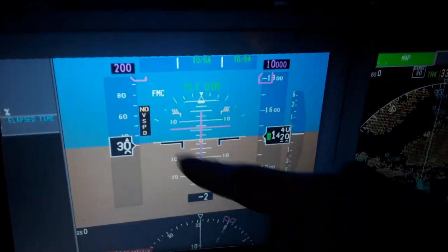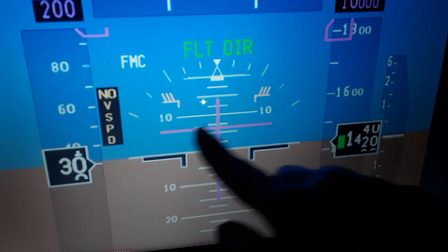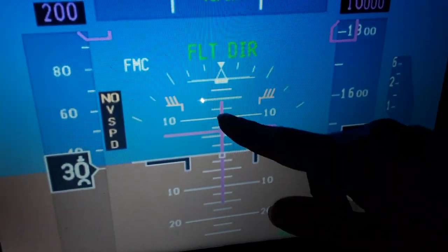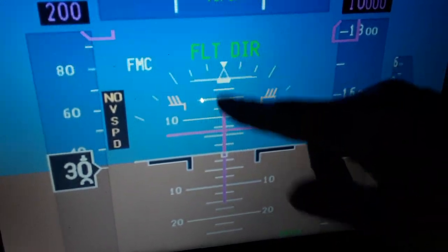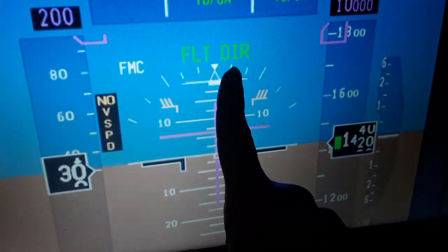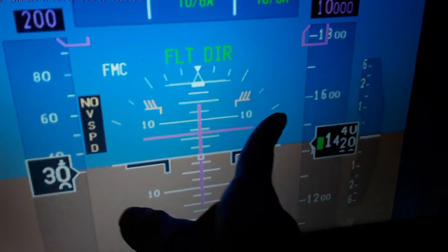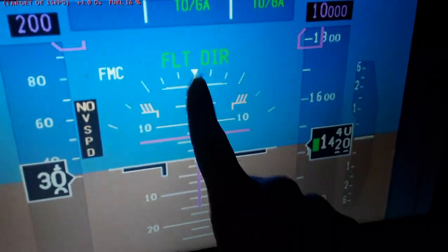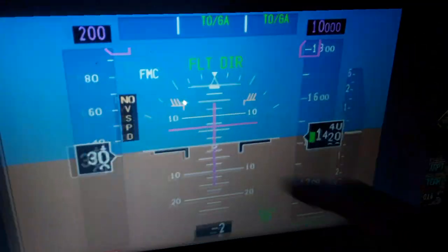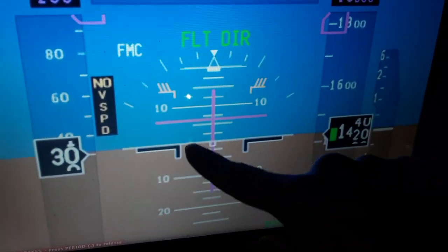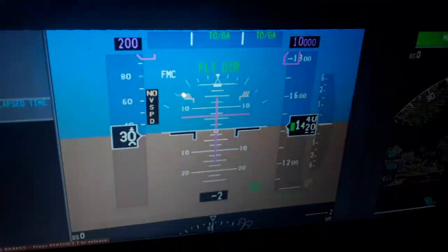We have also the artificial horizon with the attitude indicator and the flight director crossbars, this purple. We have the pitch ladder in degrees, 2.5, 5, 7.5, 10, 12.5, 15, 17.5, 20 for pitch up or pitch down. Also the bank roll of the aircraft, you can monitor like 5, 10, 20, 30, 40 degrees when making right and left turns, and also the side slip indicator. Also you can see the wings of the aircraft. This black L symbol is the wings level. When we fly, you're going to see them moving around.